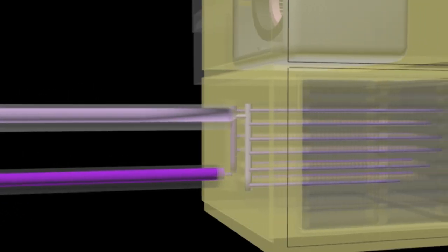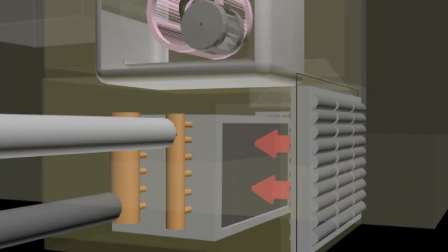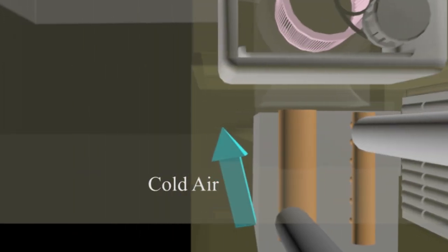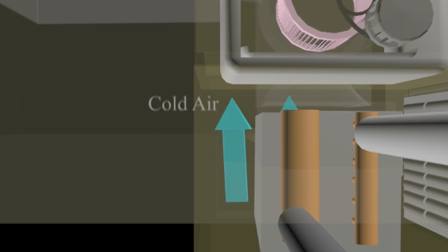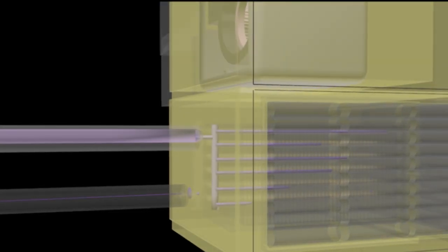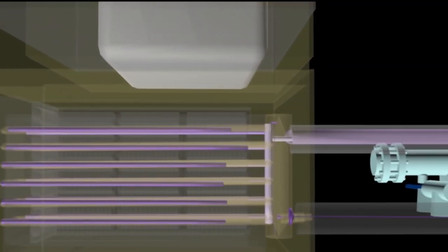In air handling units, chilled water will then pass through the cooling coil. In the cooling coil, the hot air will go through the cooling coil and switch to cold air due to the heat transferred to chilled water. Cooling coils commonly used in this system are tube and fin. After absorbing heat from the hot air, the chilled water will be known as chilled water return. Normally chilled water return pipe will be colored with light blue.